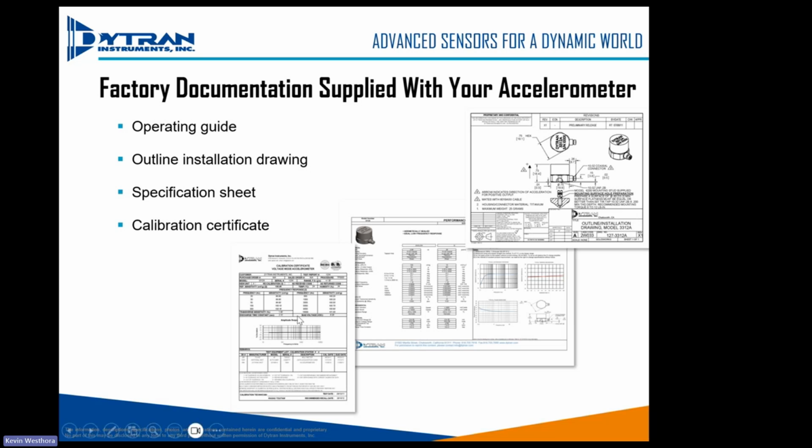And then the last piece of documentation here is the calibration certificate. You'll notice in the top right, it says A2LA. Again, we're accredited to 17025, so every sensor comes with this certificate. We give you 10 points of data. We start at 20 hertz and go up to the full scale frequency of the sensor, typically 10 kilohertz. And then we plot those data points here to give you a typical frequency response curve.